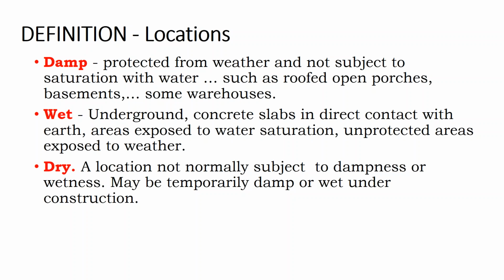The difference with PV wire is that it has a thicker jacket. And up on a rooftop, that thicker jacket has some advantages. Now, the thicker jacket is there because solar arrays at the utility scale can go into voltages that are much higher than what you see in a building. And I always like to point out, solar is done at 600 volts, and even your larger big box stores like Best Buy, their building voltage is at 480 volts, three-phase. Solar at 600 volts is very high voltage. It's much higher than your electrical outlet that's at 120 volts.